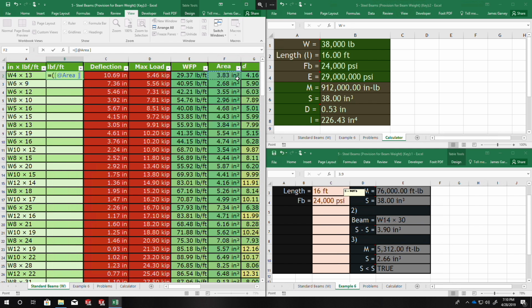I'm not just multiplying by 12, I'm actually multiplying by 144, which is 12 squared, times 144, and then times density, so parenthesis again, that's, as I said, 0.28 pounds per cubic inch, so I need to multiply that by 12 cubed, and it's multiplied because it's pounds per inches cubed, not just inches cubed.